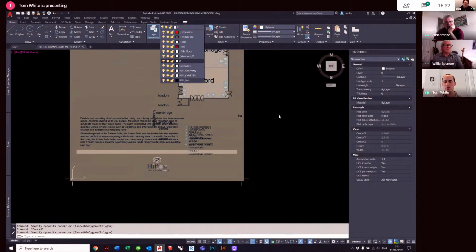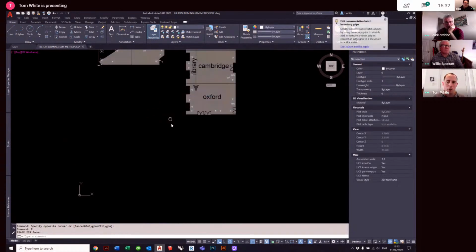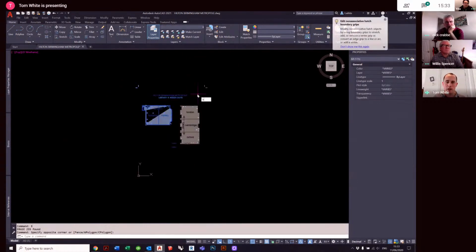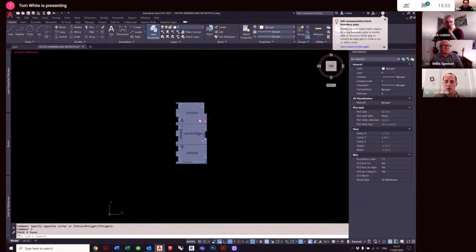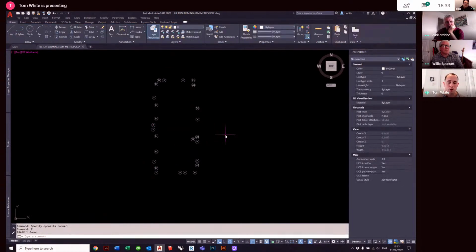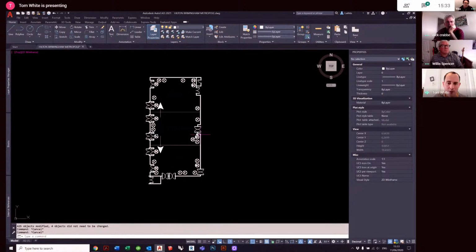So if I was to print a PDF from AutoCAD and import it again, it would actually have the layers that I've named. So what I'm going to do here is a little bit crude, but I'm hoping that it's going to help Dick, who's going on a site survey tomorrow. I'm going to delete a few items, but I can't really see what I'm doing. So I'm going to use a command called set by layer, select all the layers that are left, and press enter. And so we've got a better understanding here.